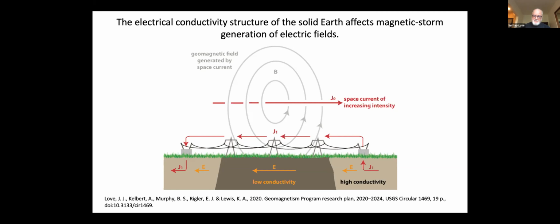The power grid is supposed to be alternating about a zero baseline, and the system is grounded because they seek stability for the system. But during a magnetic storm, that stability is disrupted, and we have these quasi-direct currents flowing through the system. It causes, in particular, malfunctions of transformer systems and distorts the alternating current waveform, and that leads to all kinds of problems. It can trip relays, it can damage transformers. In that picture, remember I showed you a damaged transformer, it can cause problems with the operation of a power grid.